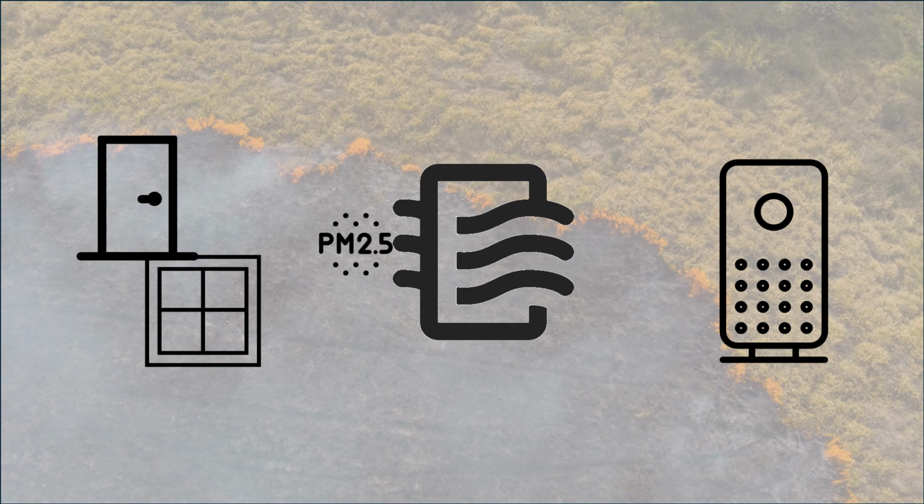During poor outdoor air quality events like wildfire smoke, there comes up a bigger challenge. This could also be true for buildings which are located closer to major roads, when the traffic means that you have poor air quality around the year. We need to be careful about our outdoor air intake for ventilation under such situations.